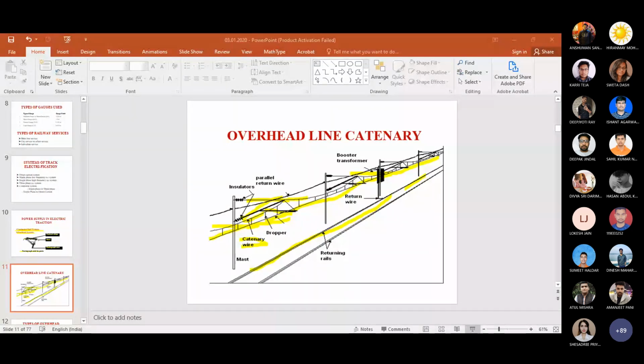It is a DC motor, so there is a problem if you directly change the polarity. Whatever residual magnetism is there, if you reverse the polarity it will be reversed, and that may damage or demagnetize the residual magnetism, which can affect the motor. You cannot stop that residual magnetism. That's why there is the changeover switch.